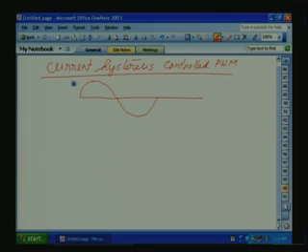So, we use PWM so that the current ripple is confined to a hysteresis band, so that the average variation of the current is nearly sinusoidal. So, we switch such that we introduce an envelope along this reference current.